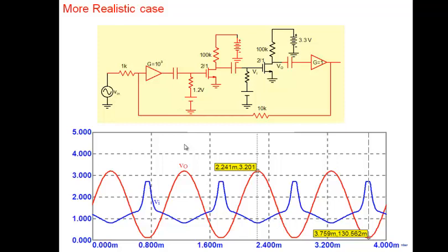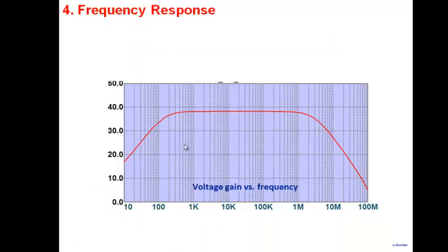Yes, the gain will depend on the frequency. As you go to higher frequencies, the overall gain of the amplifier drops, the open loop gain drops significantly, and that may have an effect on the distortion also. And so the bandwidth of the circuit will be down. Bandwidth is where we are; that's the next topic we have to discuss.